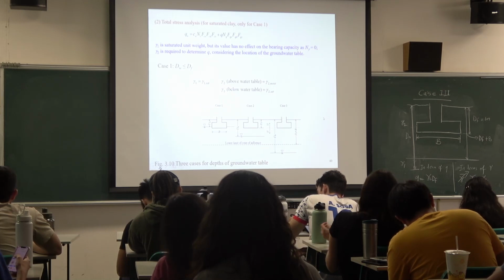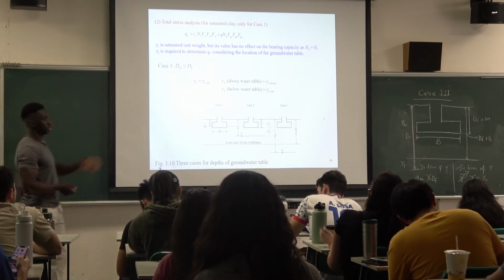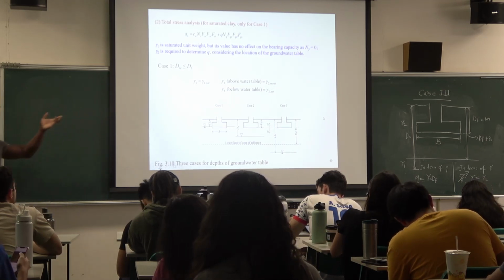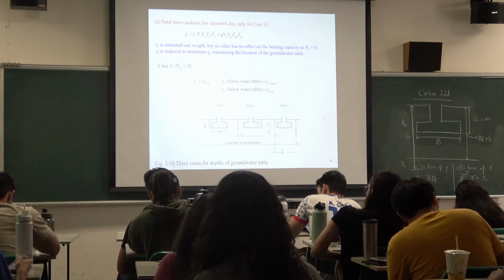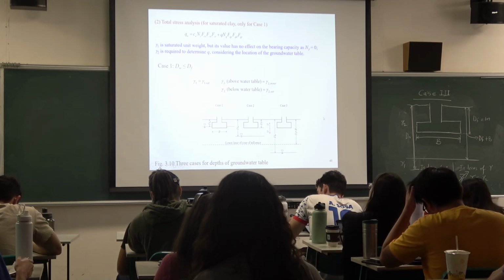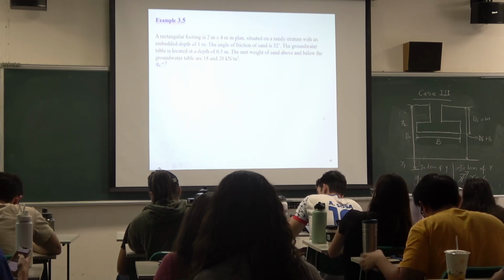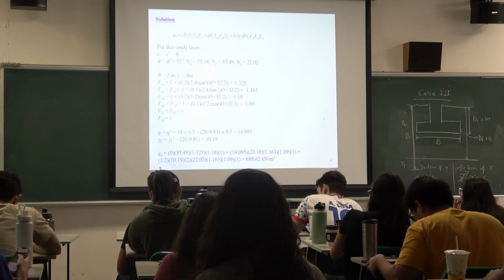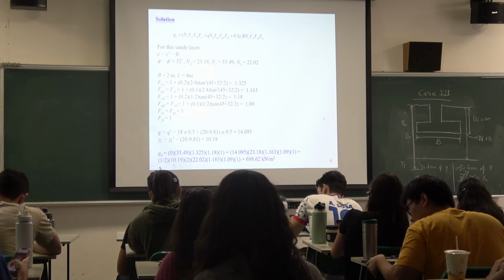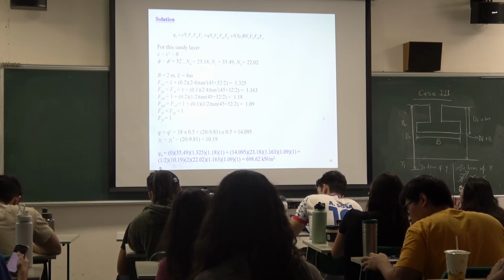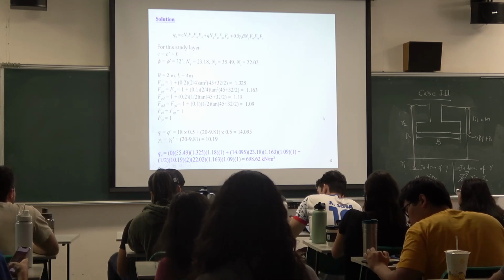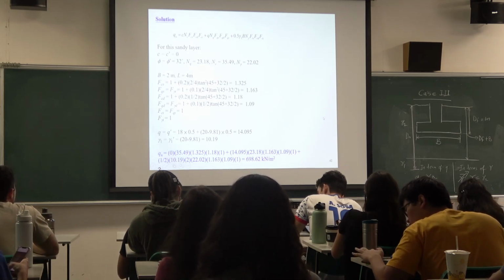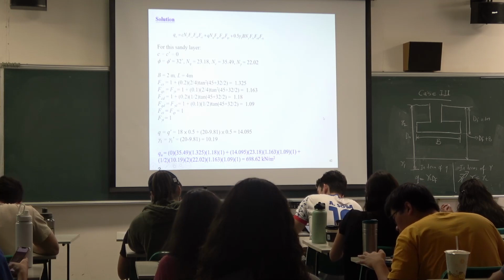Okay, and cu here typically is still the same cohesion. They use u just to signify that it is the undrained condition. Okay, and then this is similarly the same problem. So you can see how we find the shape factors, the depth factors, and the inclination factors. They are all still pretty much the same.